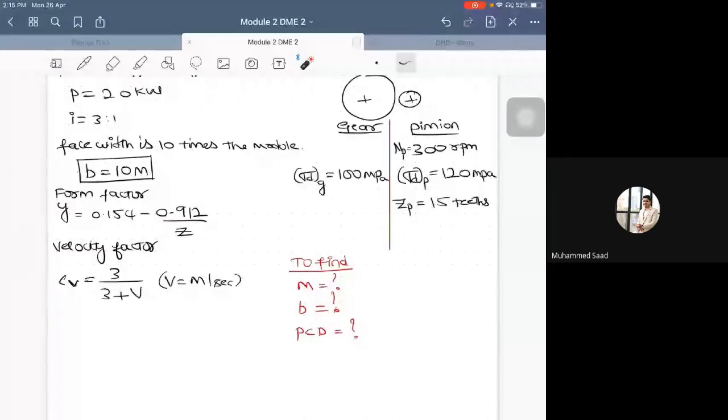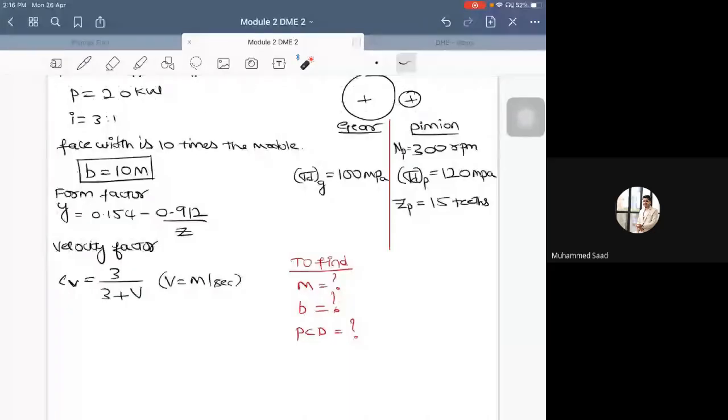Yes, it is a weaker section. But you have to prove it numerically with the parameters. Sometimes if the pinion material is so strong and the gear material is very soft, the gear could become the weaker part. Getting my point? So it is always better to have a check.